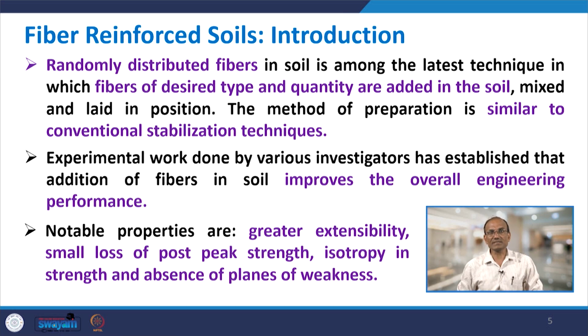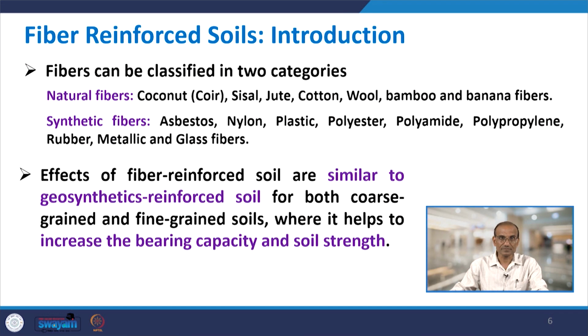Experimental work has been done by various investigators, and it has been established that addition of fiber in soil improves the overall engineering performance. There is no doubt about that. If you add fibers in the soil, they will improve its engineering performance, and notable properties which improve are greater extensibility, that means its ductility will increase. Then you have a small loss of post-peak strength, isotropy in strength, that means in all the directions the strength will be similar, and then absence of planes of weakness. So, these are the plus points when you add fibers to the soil.